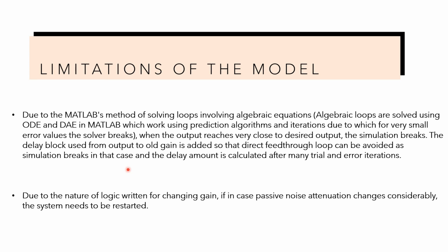in Matlab, when we have such loops, they are known as algebraic loops. Those loops are solved by Matlab using some prediction algorithms, and it is also an iterative process. So when our error becomes smaller and smaller, it becomes difficult for Matlab's algorithm to calculate the proper values. Hence, our simulation breaks.